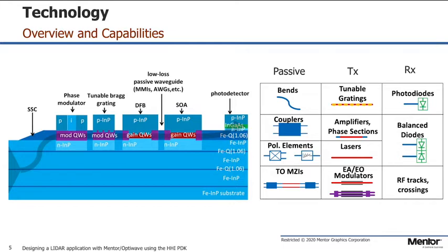Those are purple. They're sandwiched in a PN junction, and in red, you can see the ones that are used for gain. The blue layers, in which light propagates, indicated with the transparent gray line, are the passive waveguide layers, which are ion doped, so they form a semi-insulating layer. So by making use of the PIN structure, photodetectors can be realized.